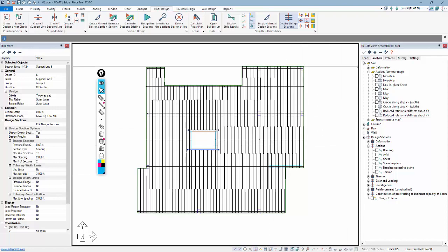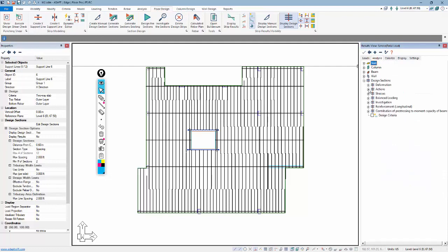And that's all judged and designed, we'll call it, through requirements that are given in whatever design code you're working in. Some design codes are a little more lenient with the ability to exceed an allowable stress, but then add reinforcement for crack control. And then there are other codes where you have to meet hard limits for allowable stress. So if we look at, let me go ahead and collapse that, I'll come back to design sections, excuse me, stresses.